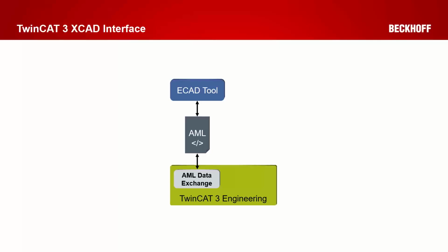If you would like to, in addition, use the advantages of the XCAD interface, like adding the PLC content, adding links automatically, comments, rename the PDOs, or adding configuration templates, then you can install TE 1120, the XCAD interface, and it's going to be available then.